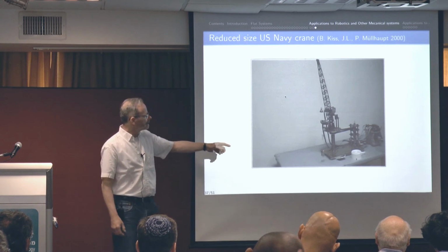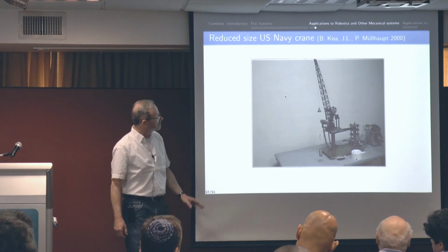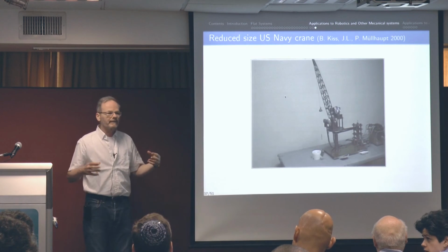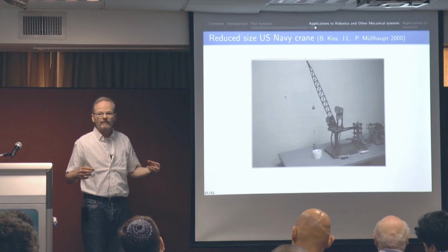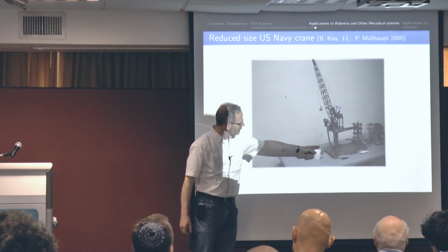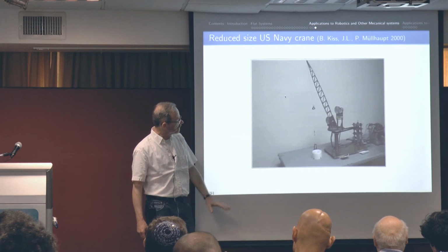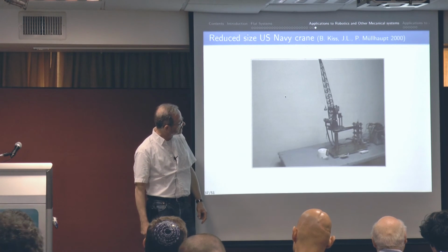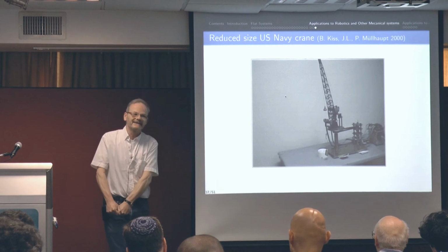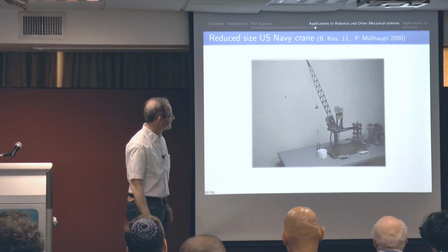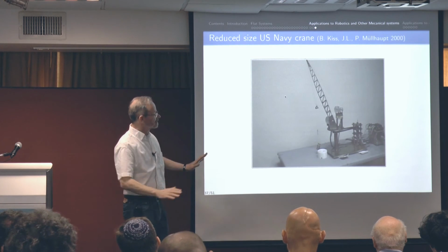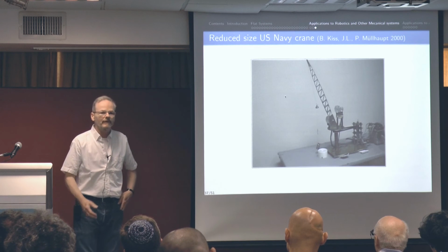So you can stabilize without sensors on the load, only with position sensors on the motors. And finally you follow parabolas, horizontal parabolas, and like this. This one is, I think, the most impressive because you have to throw it away and then get it back. And this is all done with the formulas obtained by flatness.